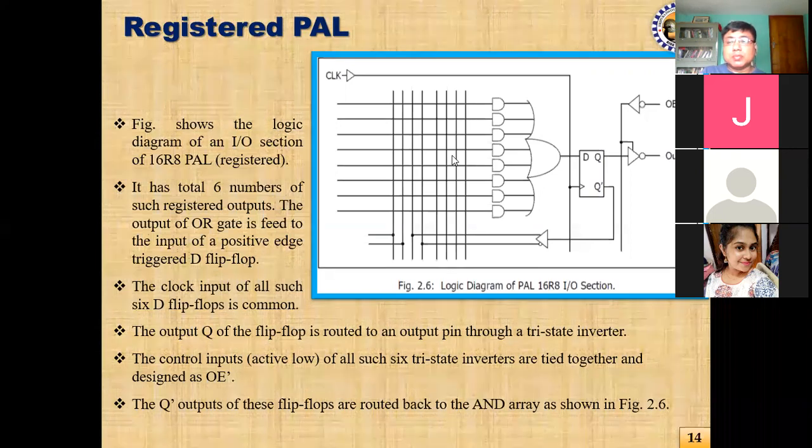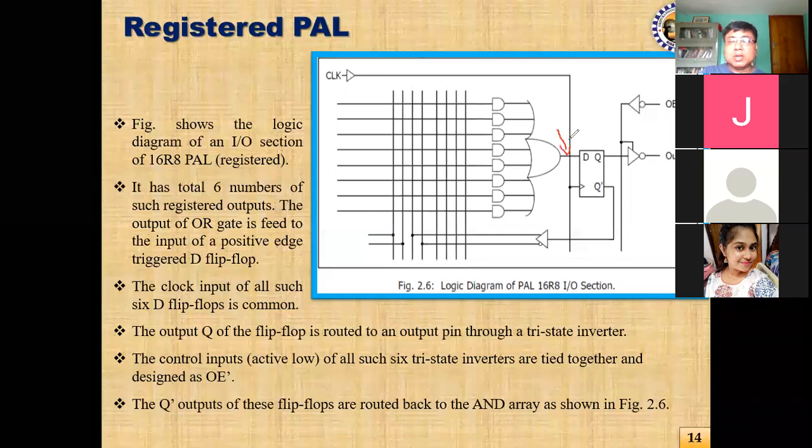See the Boolean expression that we have implemented over here. It can implement a maximum of 7 AND terms. If you count, you will get 7: 1, 2, 3, 4, 5, 6, 7. So there will be 7 AND gates, and one will be the control for this one, and at the output of this we can get a Boolean expression with 7 AND terms maximum.